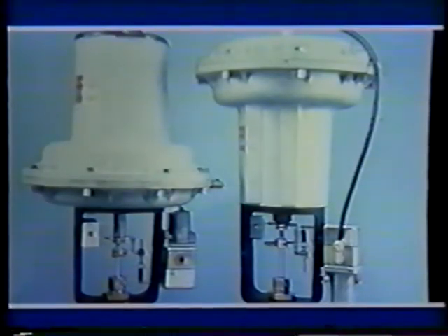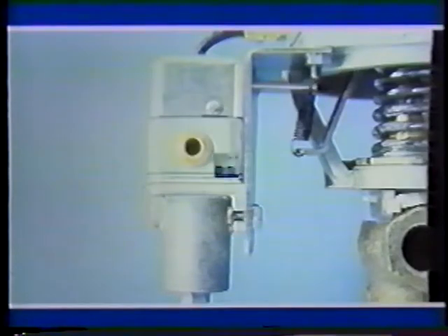The positioner on a normally closed valve does not provide additional force to close the valve, only to open it. This situation is reversed with a normally open or direct acting valve application. In that case, extra pressure applied by the positioner provides additional closing force to overcome pressure drop in the system. In the reverse acting or normally closed mode, the valve spring in the actuator must provide the close-off force.